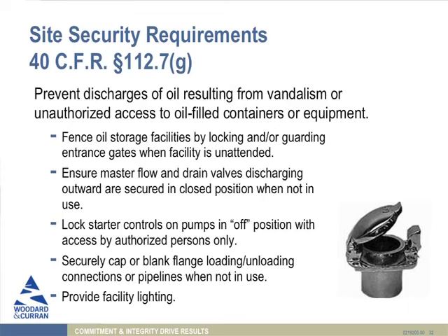Site security. The rules want to make sure that you've put in place measures to prevent unauthorized access to your facilities and damage from vandalism. So what they ask for are fencing oil storage facilities, ensuring flow drains and discharge valves are secured and in a closed position when not in use, locking up starter controls to prevent access to unauthorized folks, capping and blank flanging loading and unloading connections when they're not in use, and providing facility lighting.